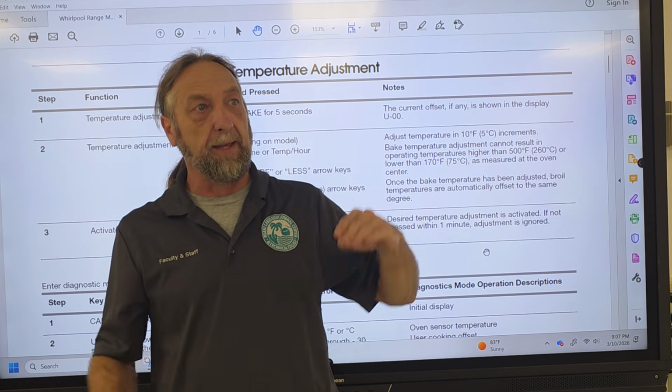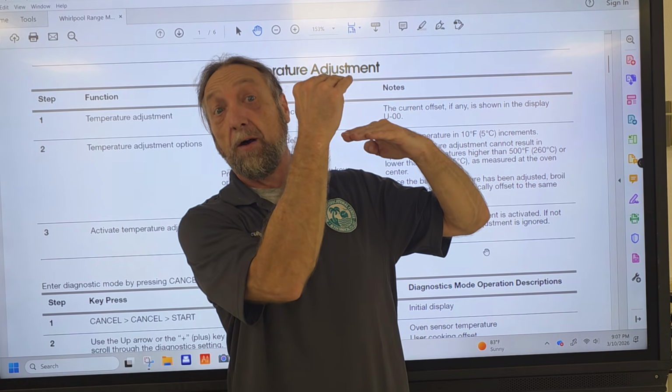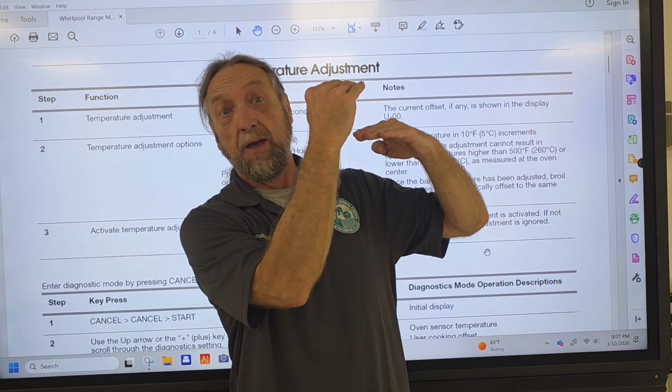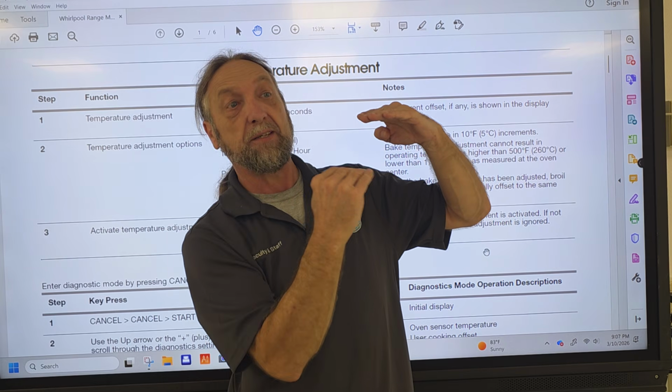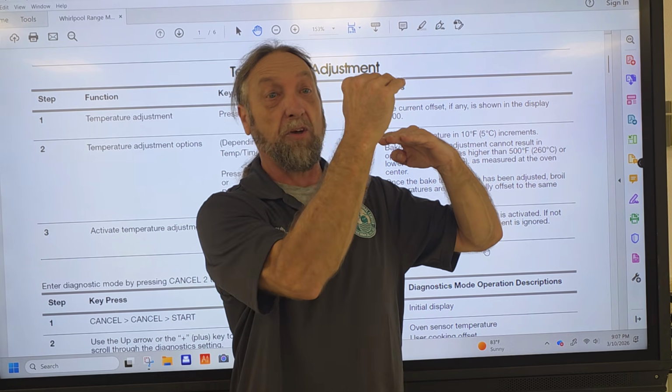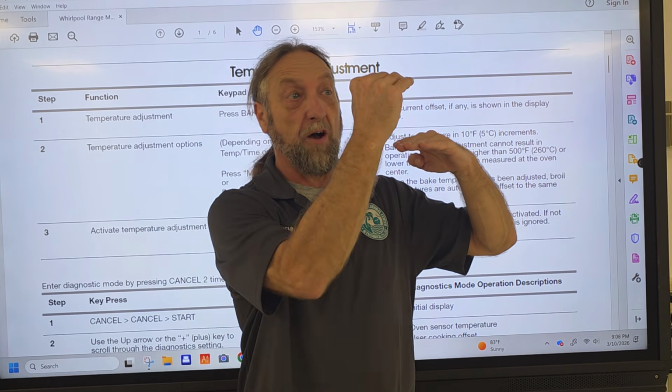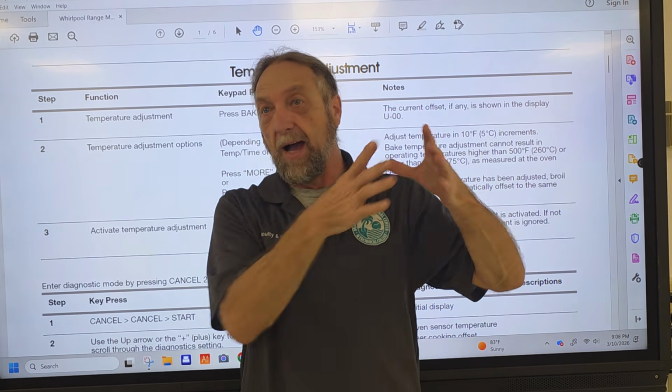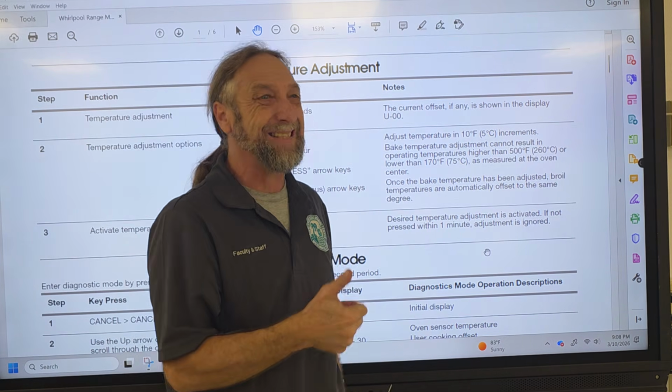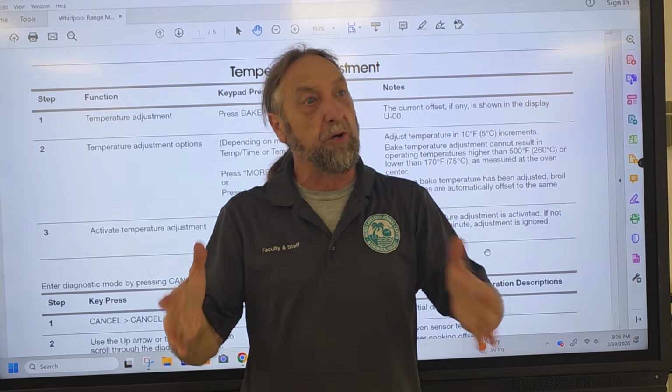What I mean by that is it comes on and it goes way over the temperature and it's off. Now it drops. I'm going to take the temperature when it comes on, goes off, comes on, goes off, comes on, and goes off. I add them together and divide by 6, and you'll have an average temperature.